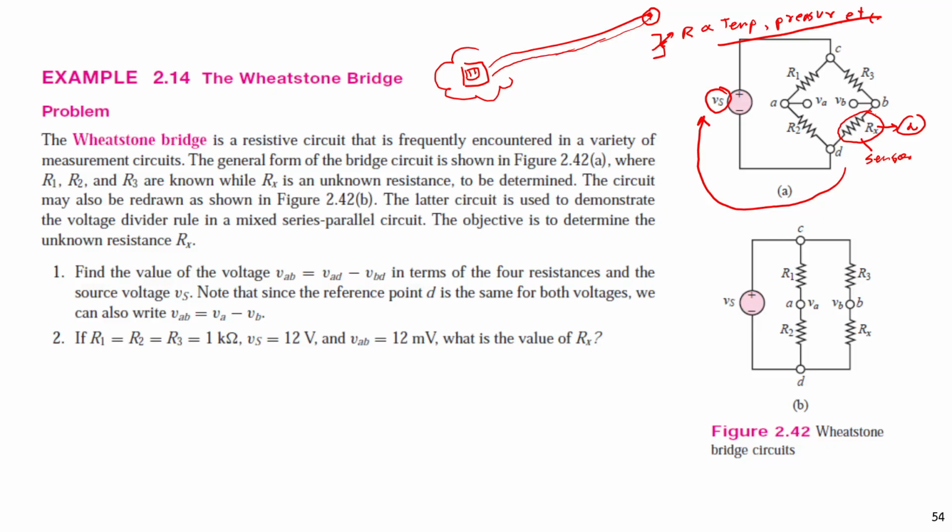Or sometimes the pressure changes and the voltage changes, so we can convert this voltage, for example 0 to 10 volt, to mean 10 to 50 degree Celsius, to show it or to use it to control something.